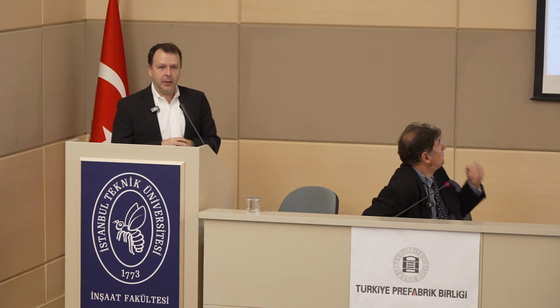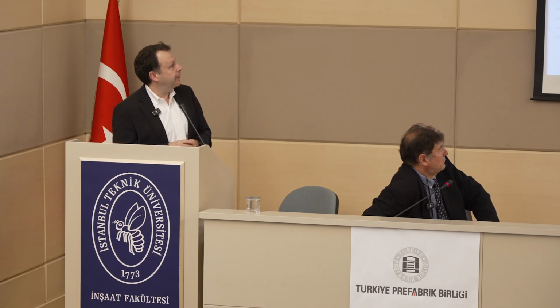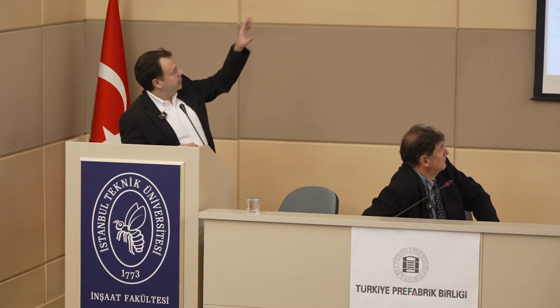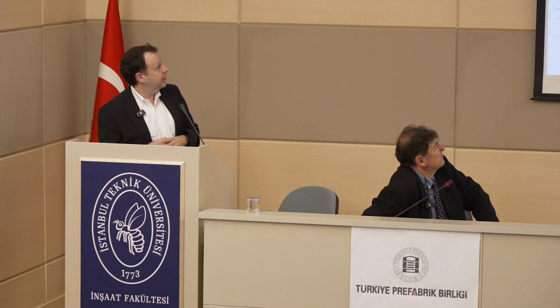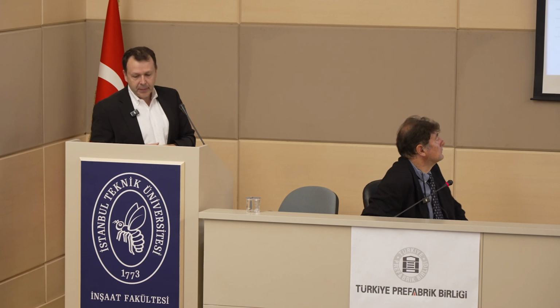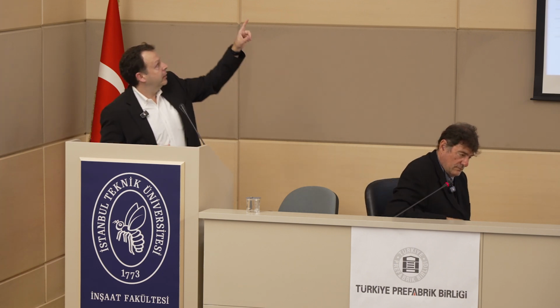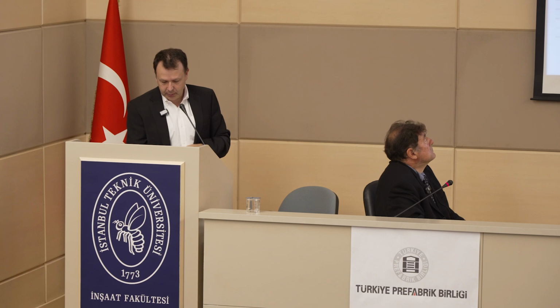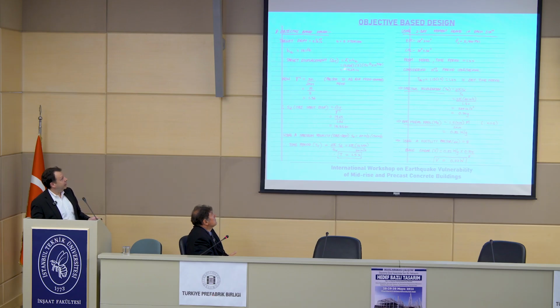Right, and so if you go through the steps that Bob had explained before yesterday, here are all the steps. And first step is you define your target drift. You may see there that it's 2.5% for 5 stories. These are in feet, but the 13.1 feet is 4 meters tall. You go and you define your target displacement, and there the numbers, it's a 2.5% times the number of stories times the height of the building. So that's how you define your value there.